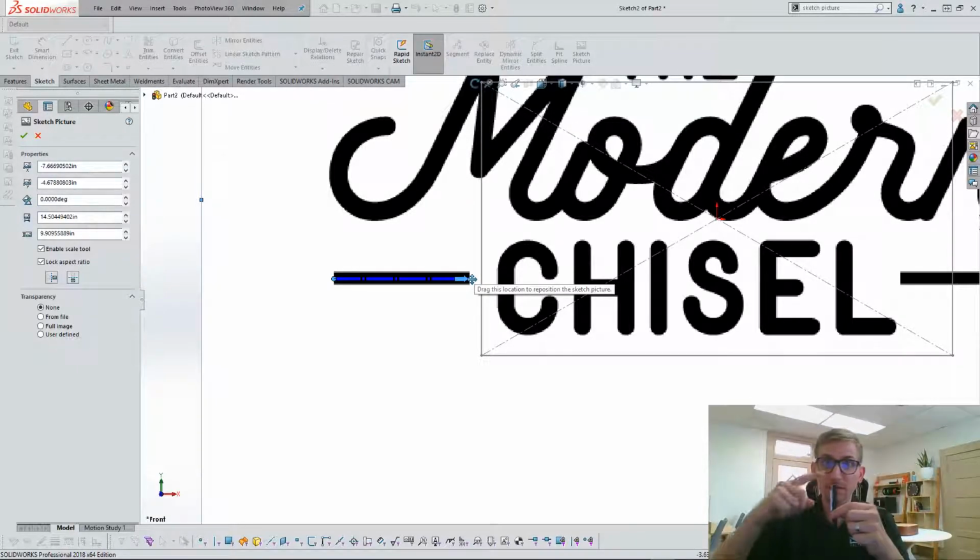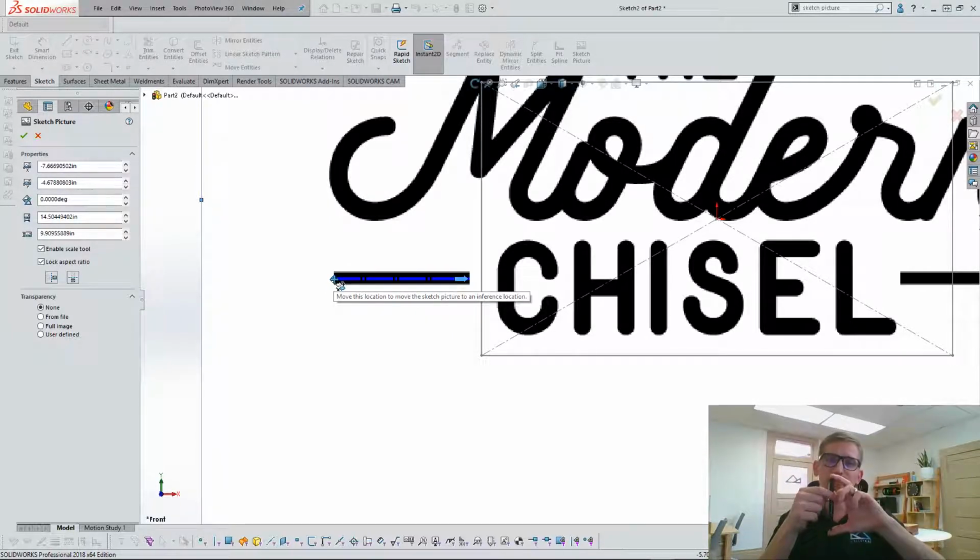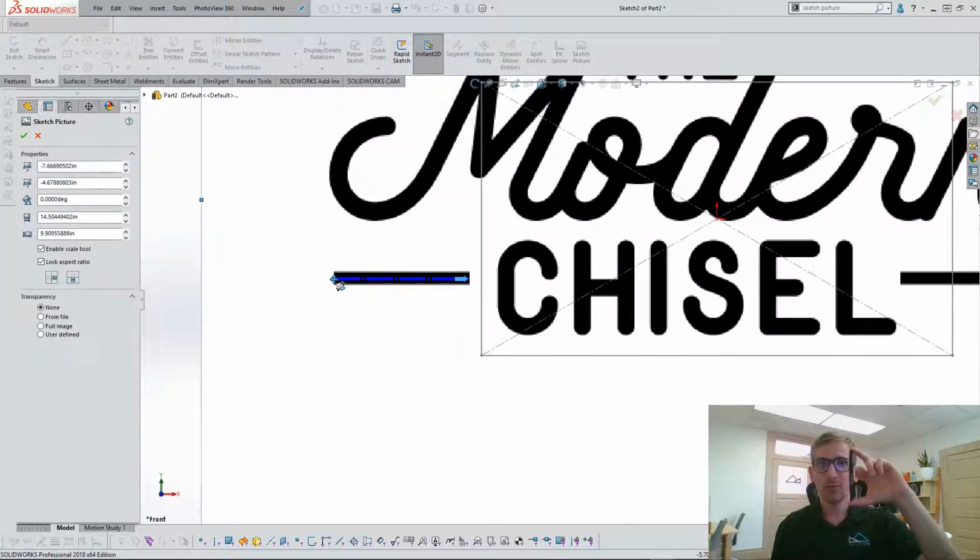With that reference line that I made for the pen application, since I made that line 5 inches, I would take my Enable Scale tool here and lock the dot up on top or on the bottom, then drag the arrow to the opposite end, make sure it's vertical, and then specify that I want this to be 5 inches tall. It will rescale the whole picture so that your pen is 5 inches tall. Pretty cool. So Enable Scale tool is a great application for this.